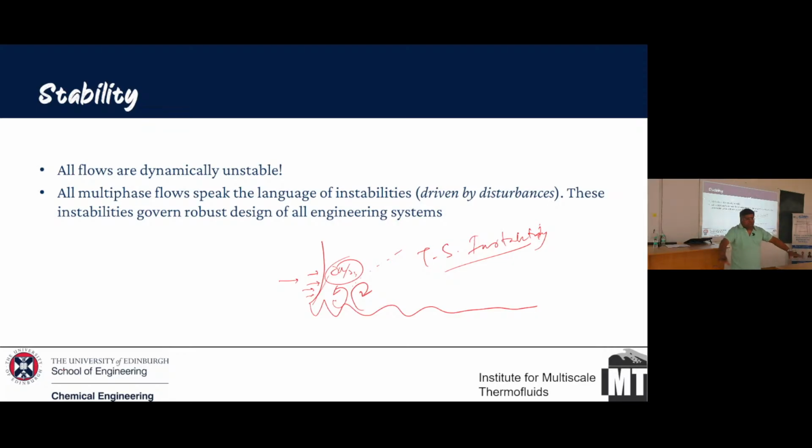In most laminar flow, in your microfluidic devices, the Tollmien-Schlichting instability is too small, so we ignore it, because it is not creating turbulence. But if you have a larger system, if you want to construct a smoothish pipe, this is what is going to play a role. In fact, in Manchester, people have created a smooth pipe which shows laminar flow at a Reynolds number of 6,000. That is an ultra smooth pipe. Obviously, practically, we don't need to make it, because everything has roughness.